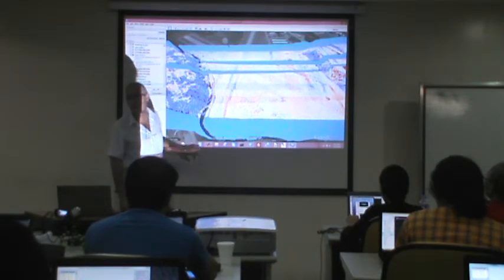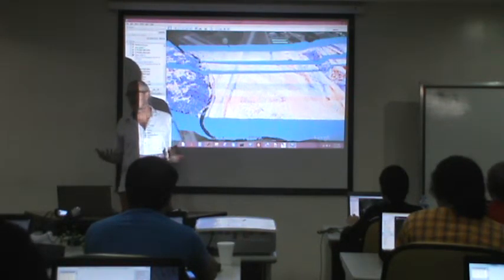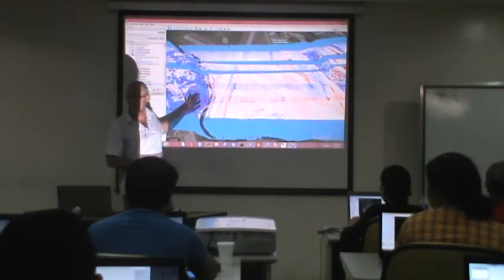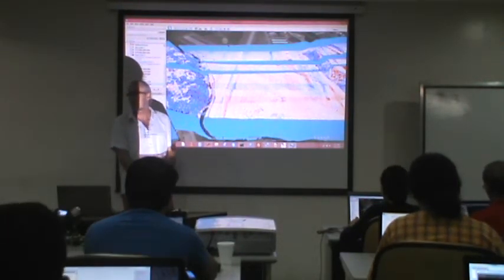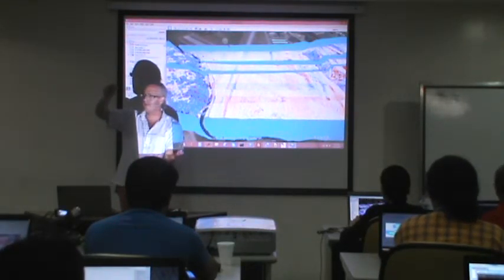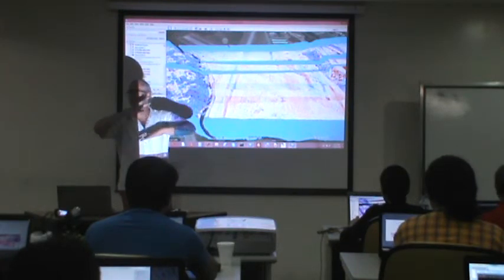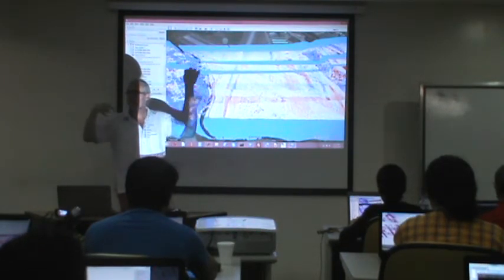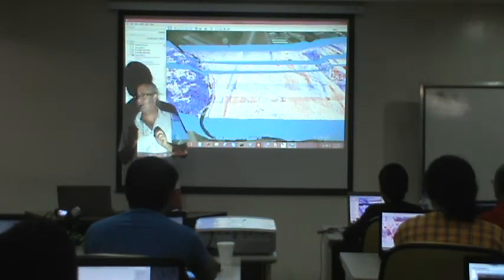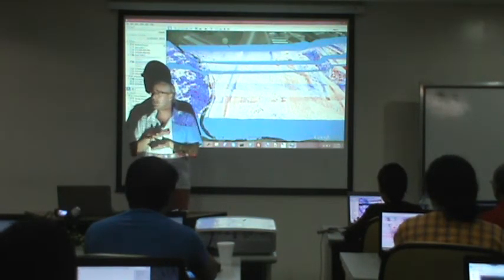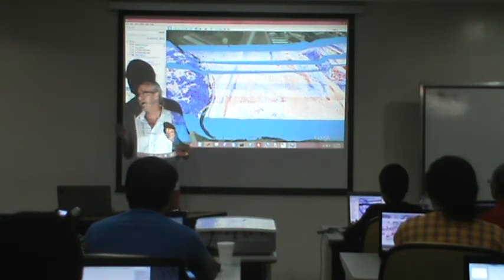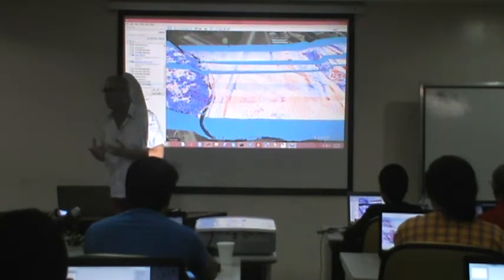But this here is forested area. And in forested area, you can't really use this for the quality check because you don't know if every LiDAR return went all the way to the ground. So sometimes it gets stuck here, sometimes it gets stuck here. So it has nothing to do with the quality of alignment, but it has to do with the different penetrations. However, in the open areas, that's where it really matters. Whenever you have flat open surfaces, they are supposed to be mostly white. And this is a quick visual check.